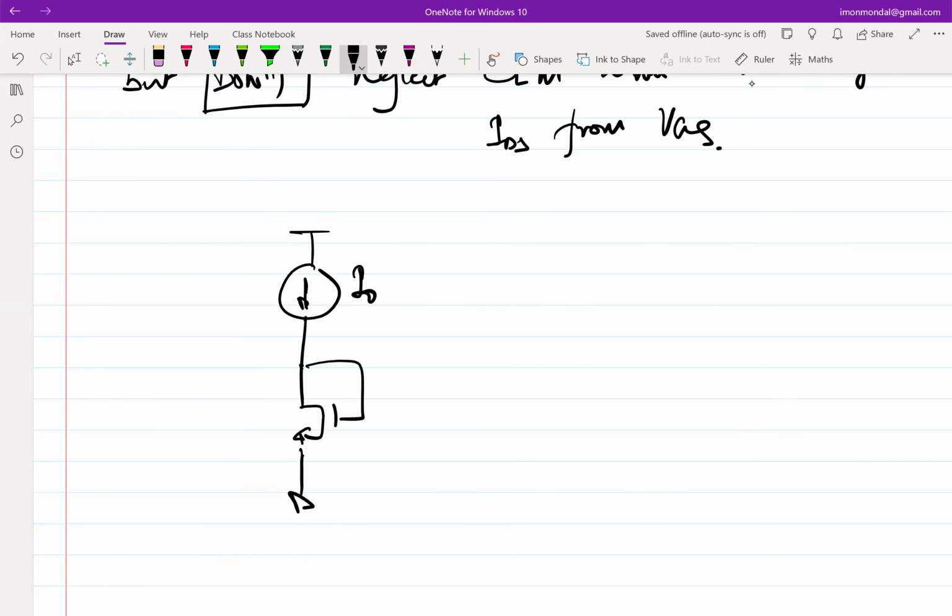So in this architecture, if I naught doesn't change, let's say I have I naught and I have VGS. I naught is an independent variable, and VGS becomes a dependent variable. If I neglect CLM and I found some value of I naught, and I'm trying to figure out the VGS, maybe that point is here, neglecting CLM.